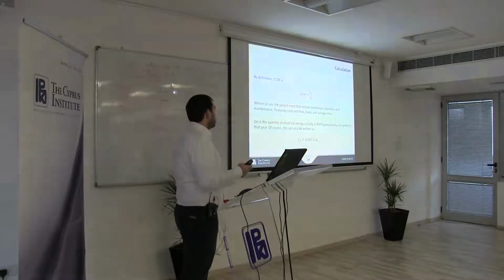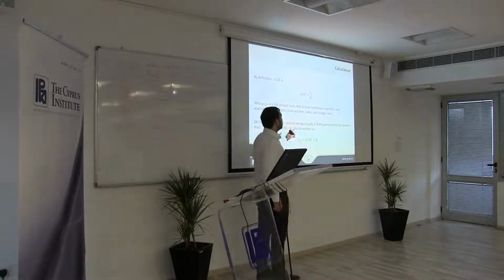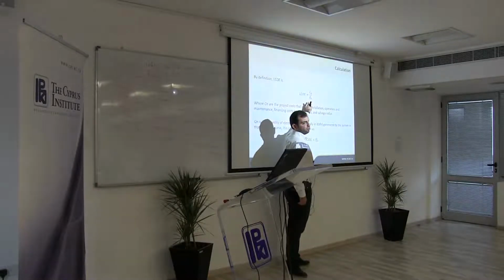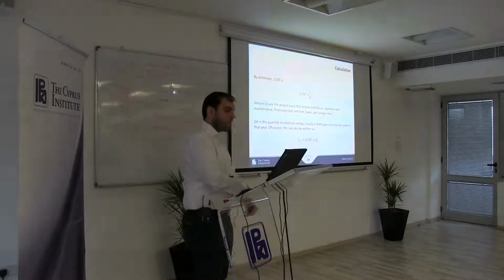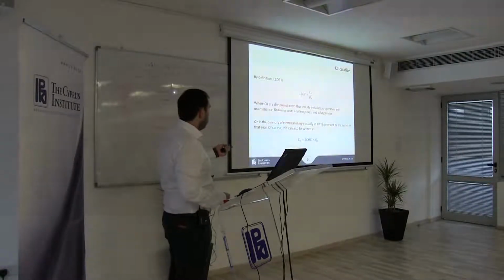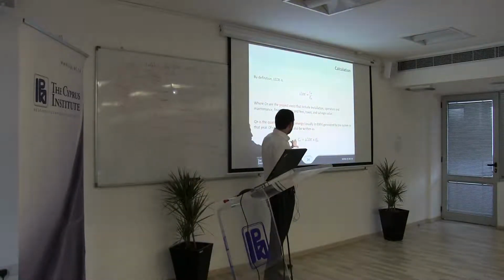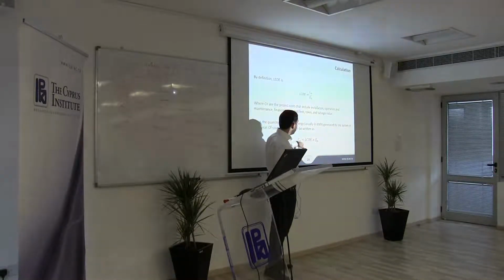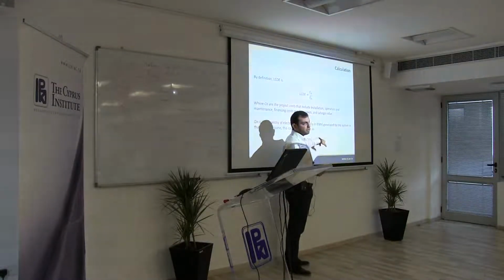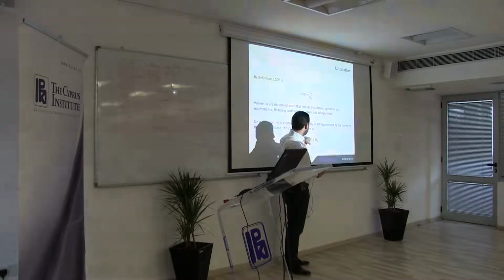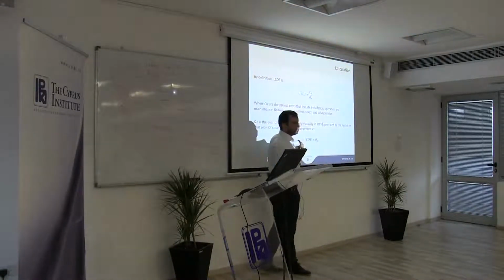So how is this levelized cost of electricity calculated? It's basically calculated by summing up all the project costs and dividing by the amount of electricity generated by the plant. So it's a relatively simple calculation, and this can be done either annually or throughout the project's duration. And if we rewrite this equation, the total cost of the technology can be estimated by multiplying the levelized cost of electricity generation times the amount of electricity. So this is expressed in dollars per kilowatt hour times kilowatt hours of electricity generated. We get dollars here.